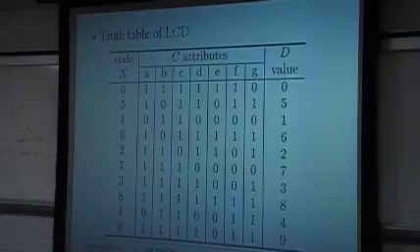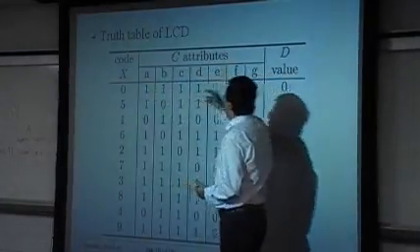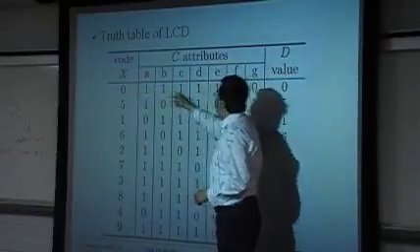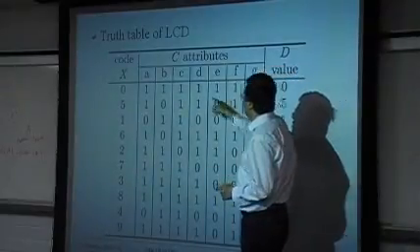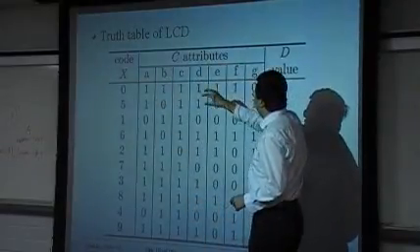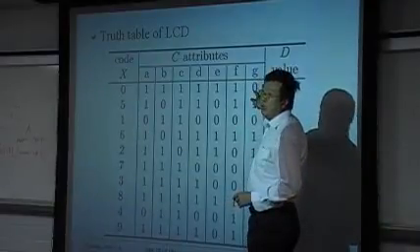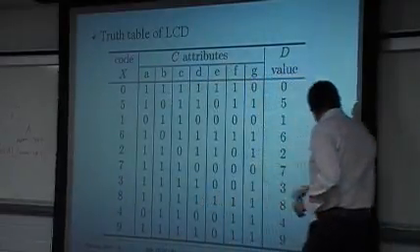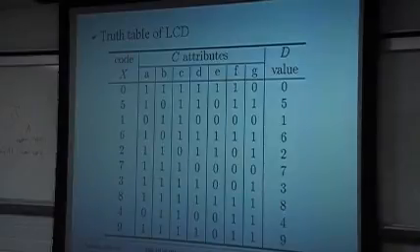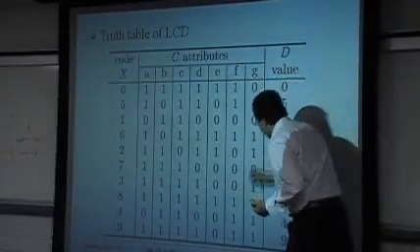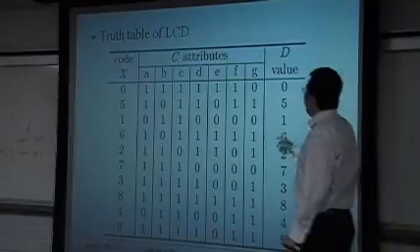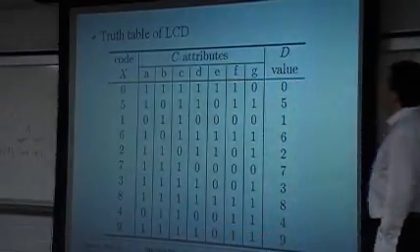So for this example, we have to create a truth table where for each value here, we will have the indicator of the 7 segments. For instance, if we have 0, we will have all the 6 elements by 0, and the middle one denoted by 0, or the other ones are 1. So we will have all this on, but this one is 0, and this one happens to be the G definition here, and it indicated this is a 0. And then for 5, we may also establish a truth table like this.